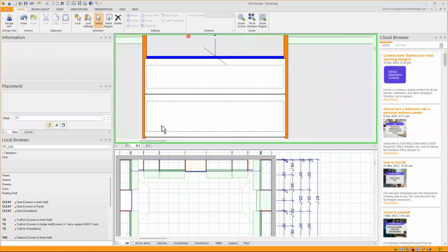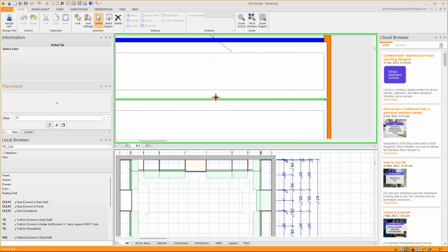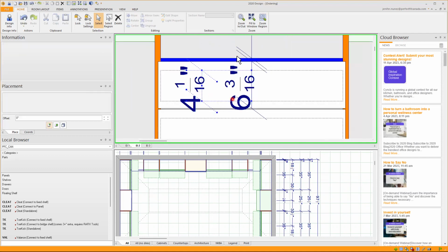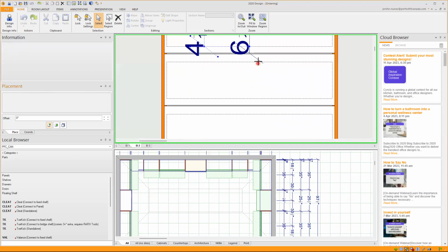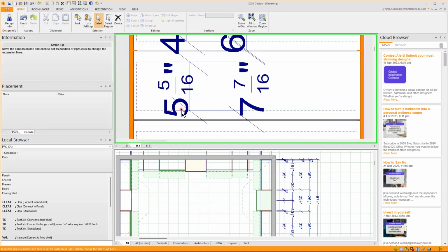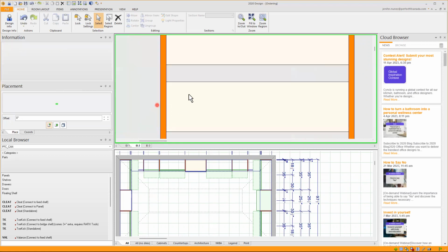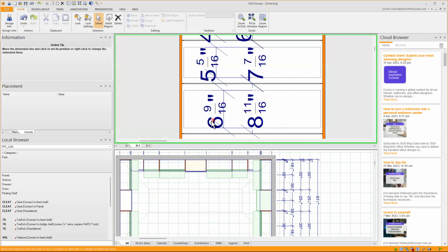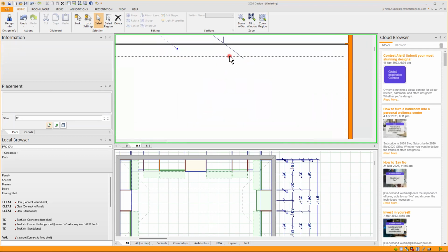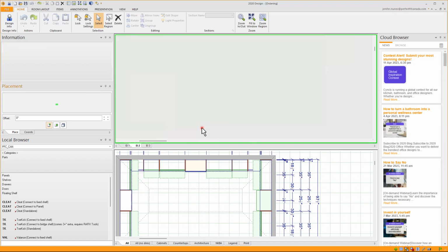And for these drawers, we usually add both dimensions. This one for the drawer front and this dotted line for the actual drawer box. And I add them to all of them. Again, just to be more clear for the installer, because all of them are different, so they know and they don't mix-match, because one can be pretty similar and then be installed in the wrong position. Anything can happen, we're just trying to avoid mistakes and provide the most information we can.